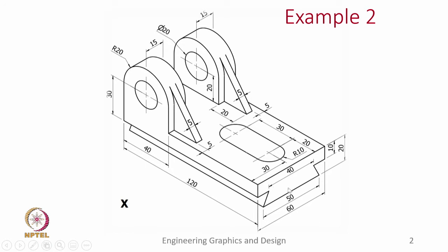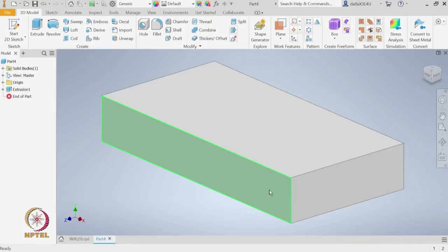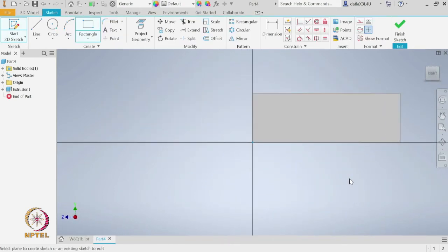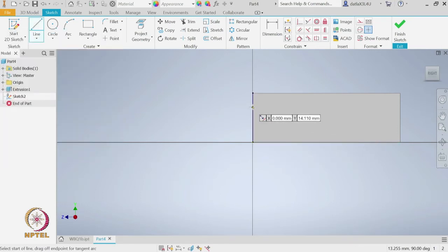To make a cut here we will select this front face and on that face we will make this section. So, we will again start 2D sketch, we will select this front face and then let us start making a multi-line. So, we need to start at the mid height. If you notice this cursor at the center is yellow, but if I keep moving up at the midpoint it turns to green. So, let us select that and then let us make a horizontal line.